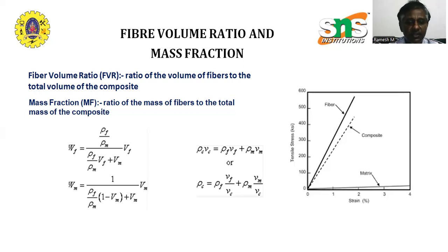In composite materials, we are not going to study the bulk modulus because we are going to focus only on a thin element. So Young's modulus will come and the shear modulus will come, and Poisson's ratio, because the lateral dimension changes due to application of the load in the axial direction. So Poisson's ratio we have to concentrate on in the elastic constants types.